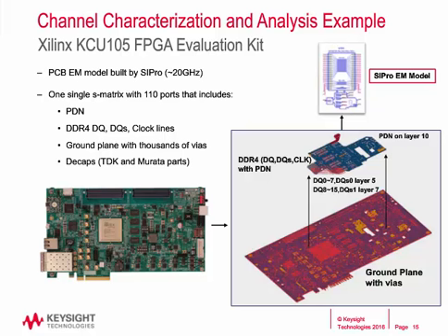So here's the simulation setup, but in order to improve the simulation accuracy, we specifically use vendor-specific IBIS models for the transmitter and receivers. In this example, we use the Kintex IBIS model for Xilinx, the transmitter chip, and Micron IBIS for DDR4 memory.